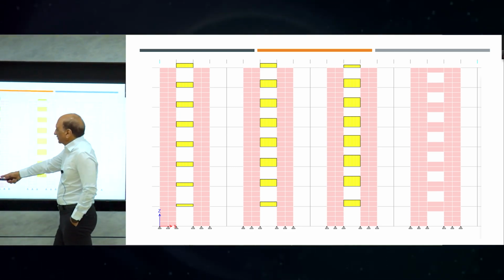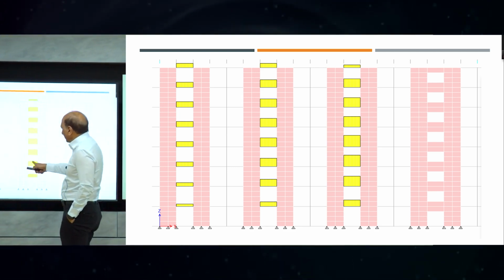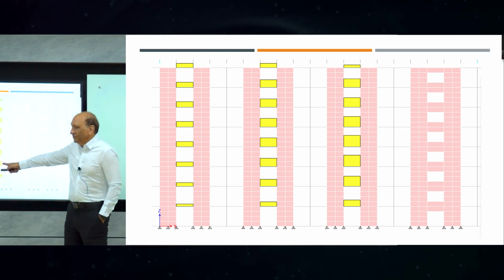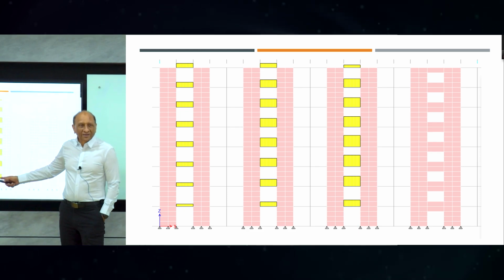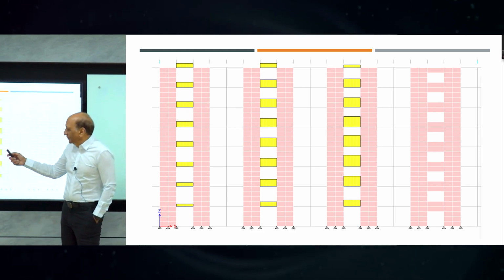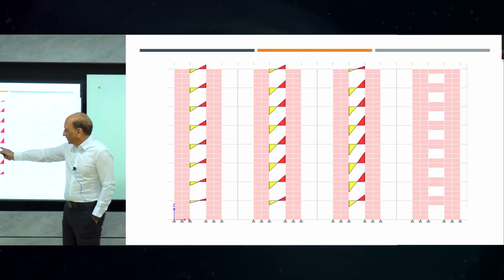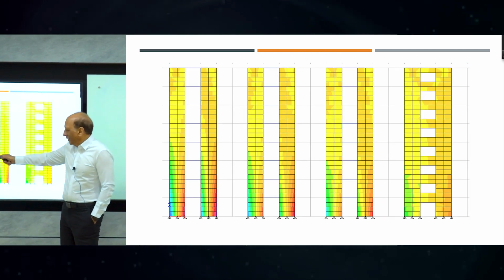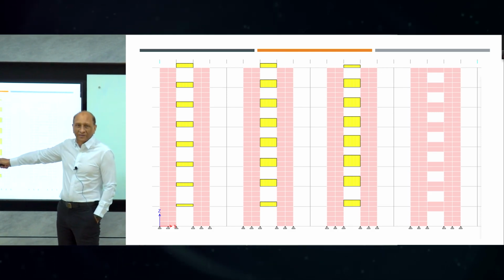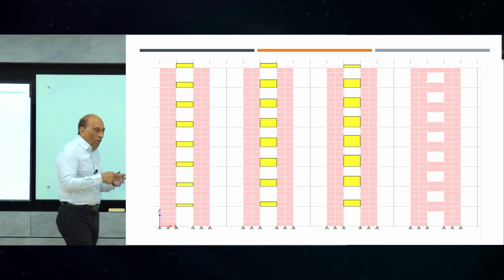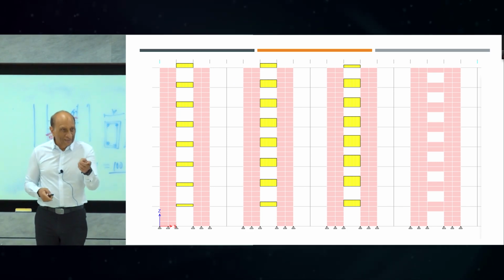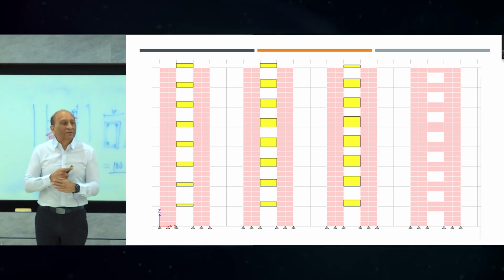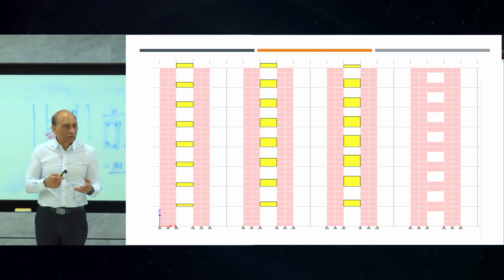Okay. So you got tremendous increase in stiffness and benefit. So that is the shear. So very small shear, very large shear, very large shear. And this shear may be more than the capacity. So that's where you limit the capacity based on actual, and then you will limit the moment based on that. Okay. So everything is controlled by the shear capacity of the link beam. So please remember, all link beams are designed based on their shear capacity. And your idea to put the diagonal is one way to increase the shear capacity and make it more ductile.